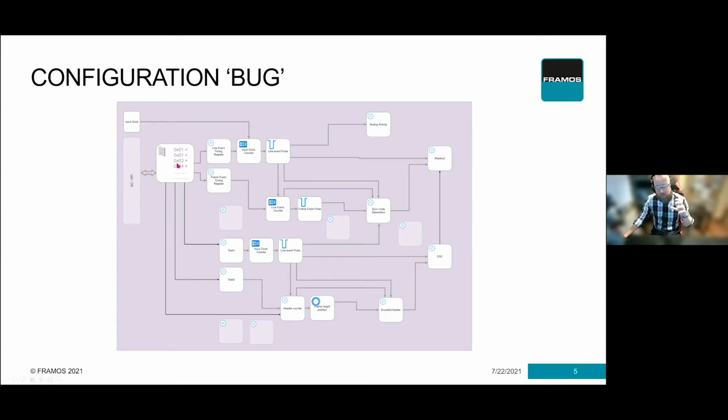But this register here, although I haven't put too much highlight on it, the numbers that go in here are the program. They are defining the hardware states for the image sensor. For example, if we accidentally change this 03 to a 0B, which is a valid hex value, the system would work completely differently.